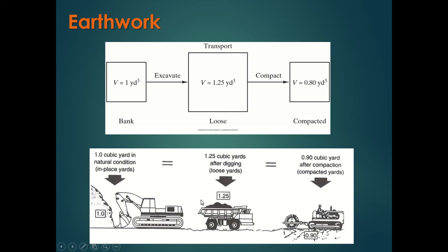So here we go. We dig it out. We haul it. And then we compact it. So in another example, we're losing 10% of the volume from when we excavate it, but we're gaining 25% volume when we're hauling it. So you just need to understand that relationship.